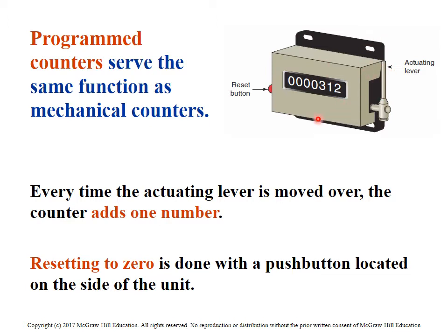And when the die went into the tool room to get its regular maintenance done on it, the tool room guy would put the new sharpened tools in it, and then hit this reset button, bringing it back to 0. So the next time that die went back into the press, it would be reset to 0, so they'd know exactly how many hits they got out of it before it needed repair.